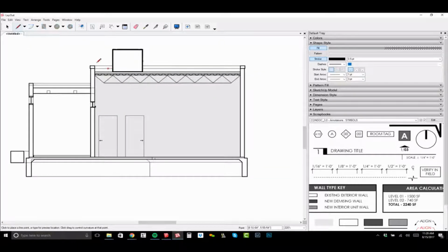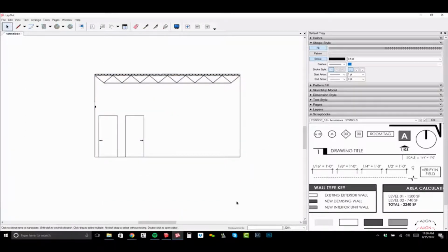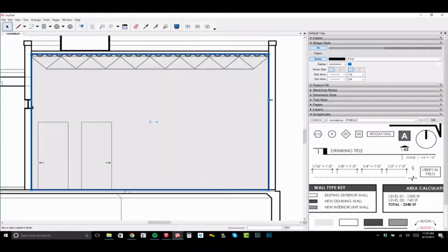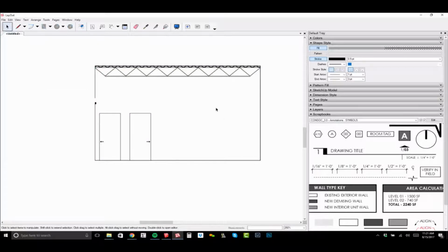Okay? So basically what I did is I highlighted the area that I want to see, and now I need to select what I just drew, hold Shift, and select the other piece. I can right-click and choose Create Clipping Mask. So I need to select both the shape and the viewport, right-click on my selection, and choose Create Clipping Mask, like that. Now, to edit a clipping mask, I can always double-click in, and you can stretch this thing around. But what I often do is right-click and choose Copy, tap Escape back out of there, and go to Edit and choose Paste, and throw that exact shape right back on top here.